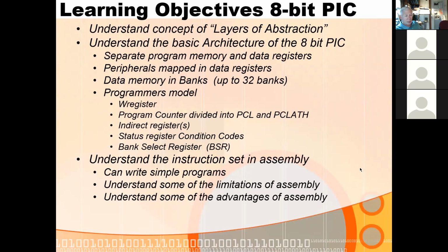But here's one of the really nice features. If you know assembly language, you can actually write your C program, and then with a special syntax, you can slam assembly language instructions in wherever you want. You just have to obey some rules. And as long as you obey those rules and use the correct syntax, you can actually insert assembly language instructions wherever you want. And that's a nice, useful feature where there are some critical timing issues.